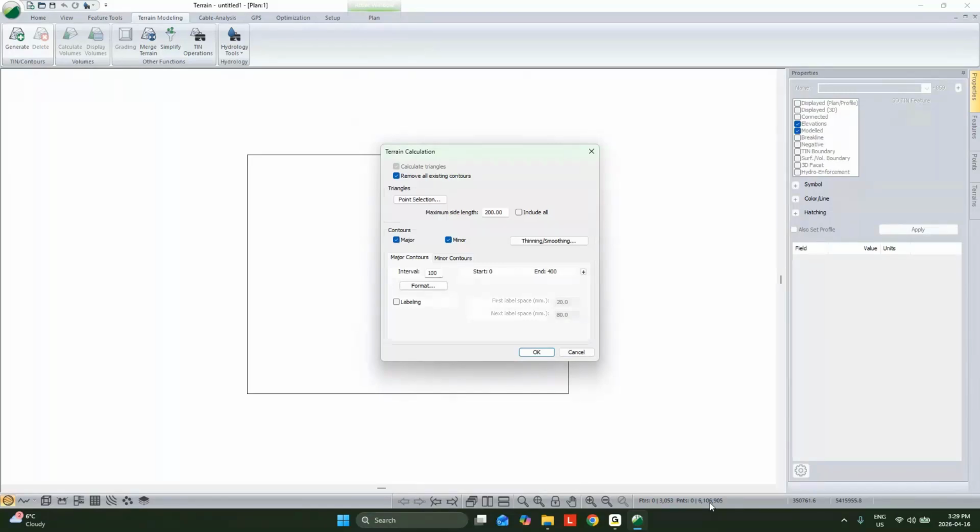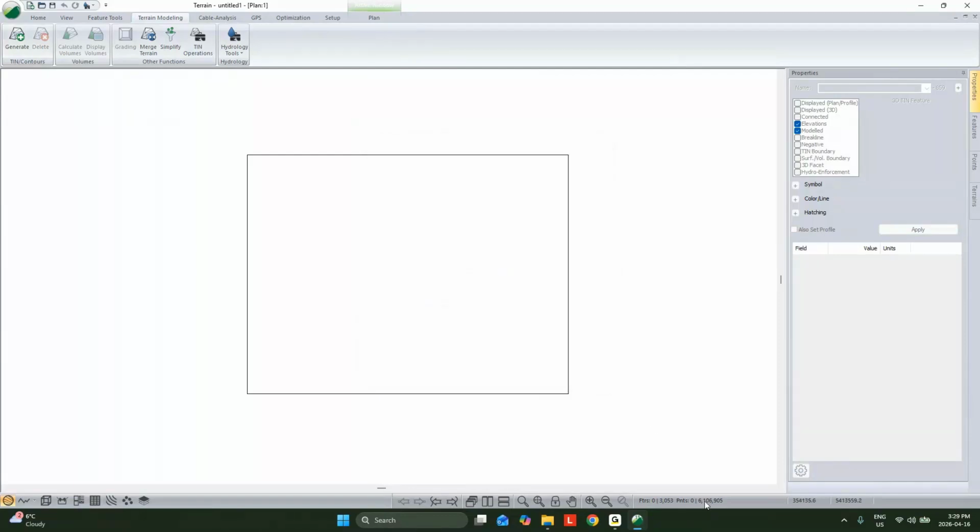It wouldn't be a problem at all here to run this without thinning. Now, if we had brought that in and we saw that that number was, say, 100 million points, well, then I'd say maybe we should use some of those thinning or other tools, like thinning and eliminating all the points outside of an area of interest. We could use that to help manage our file size.